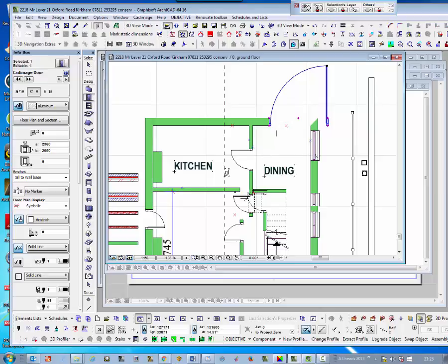When I made this room, I read my survey notes wrong. Probably should have put an extra note on my surveys, but there we are. Never mind, it doesn't matter, we can update it as we go along. So this is still a door at the moment. Now what we want to do is to make it into an opening. And if you look across here where my cursor is, if we click that button, it actually gets rid of the door, but leaves it as an opening.